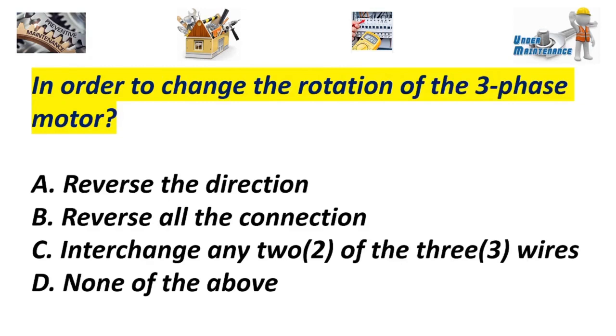In order to change the rotation of a three-phase motor, A. Reverse the direction. B. Reverse all the connections. C. Interchange any two of the three wires. D. None of the above. Answer C. Interchange any two of the three wires.